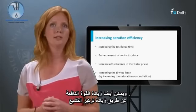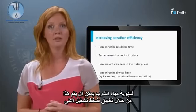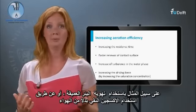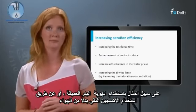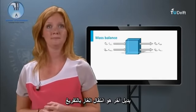The driving force can also be increased. This can be done by increasing the saturation concentration. For aeration of drinking water, this can be achieved by applying a higher operating pressure, for example with deep well aeration, or by applying pure oxygen instead of air. Another alternative is vacuum gas transfer.